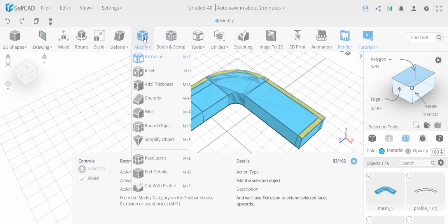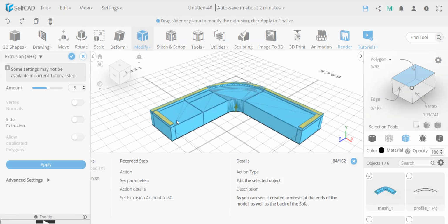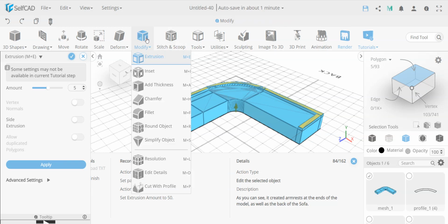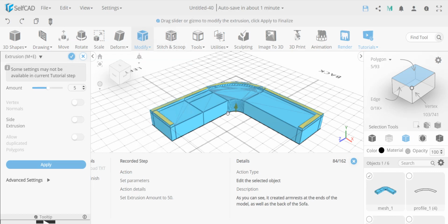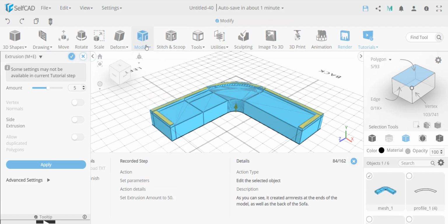Okay, now with that said, it tells me to go to extrusion. In this case, this already has some bottom faces, so actually extrusion isn't for a mesh. Adding thickness is something else. On a profile, these tools are all reusable. When it comes to a profile, you use add thickness. After fill polygons, we have a simple plane, you add thickness, and extrusion will need to add the bottom plane.